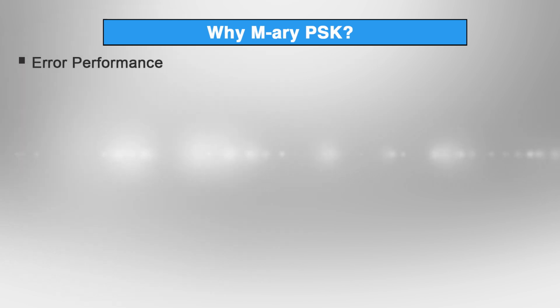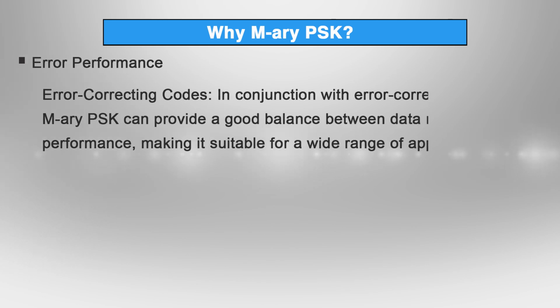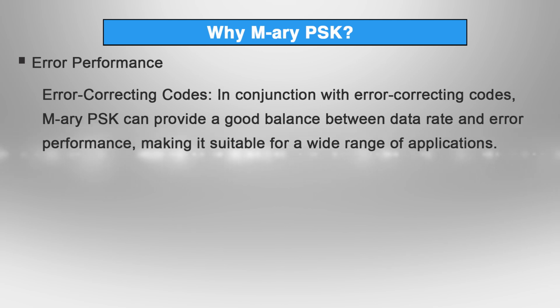Now, next point is error performance. In conjunction with error correcting codes, M-ary PSK can provide a good balance between data rate and error performance, making it suitable for a wide range of applications.